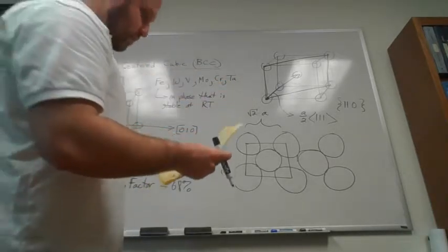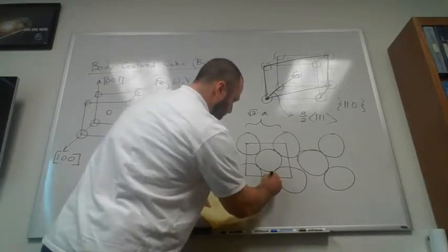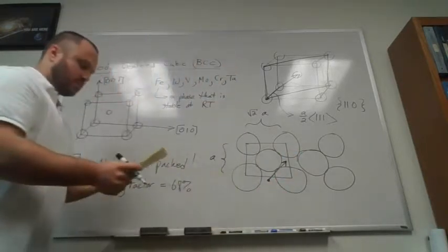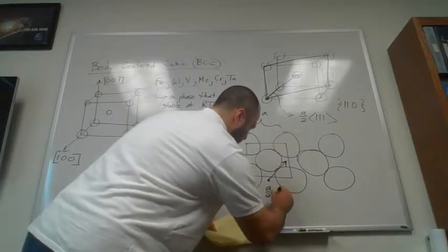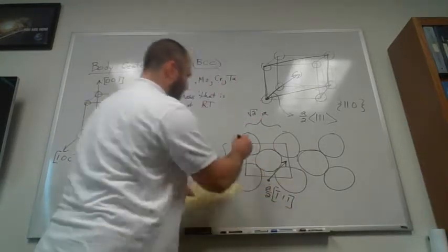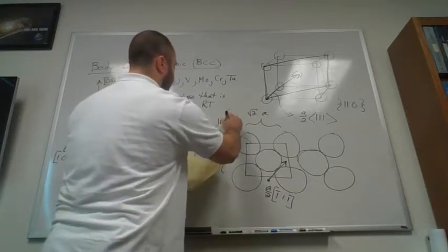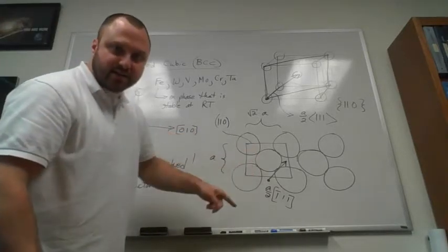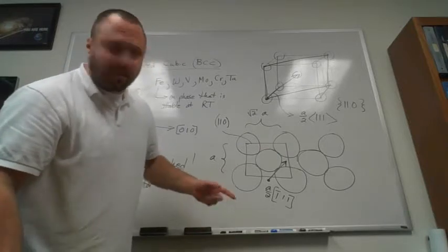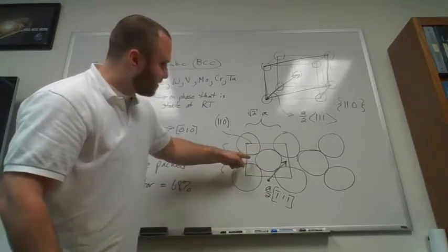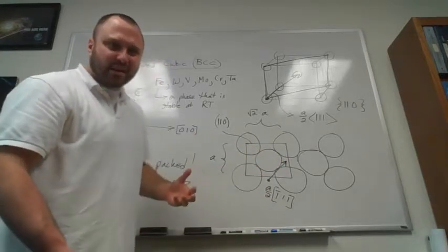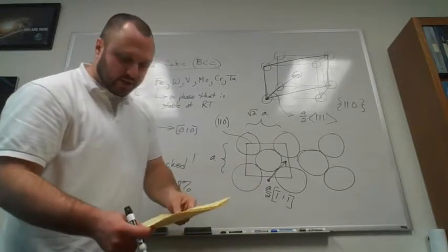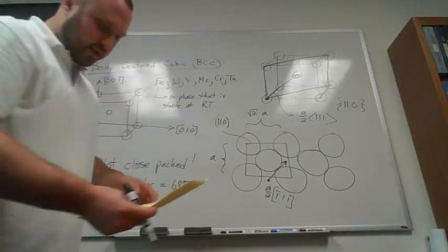And that close packed direction I just plotted, going from one site there to the next, would be a/2 [1 bar, 1, 1], if this is the (1, 1, 0) plane. All right? So unlike the FCC, we don't see any obvious other paths we can take. You could, of course, dream of, well, maybe we could go back here to the left, up and over, but that's not really making a whole lot of sense here, okay? So that would definitely be a longer path. It would definitely be higher energy. So we don't have an obvious path for partials here.